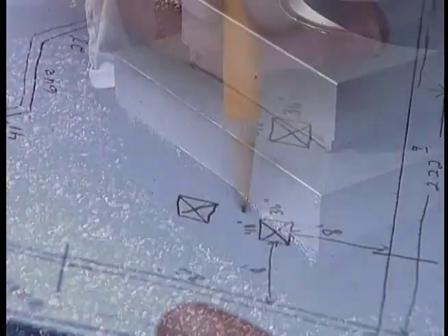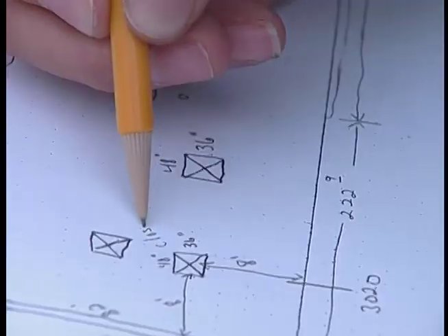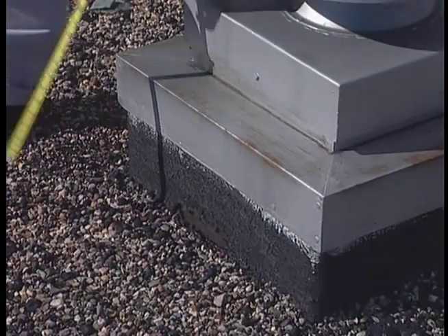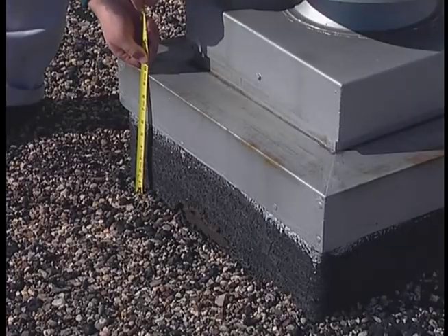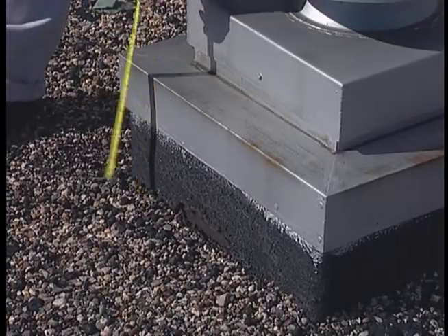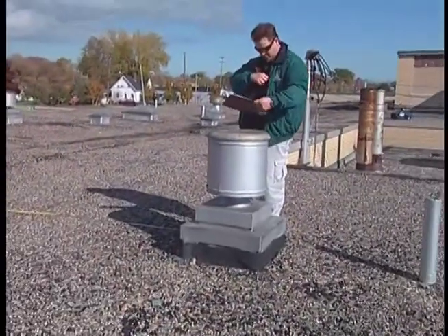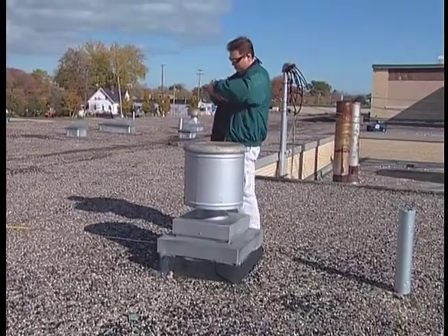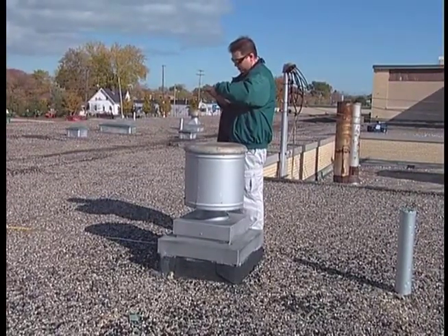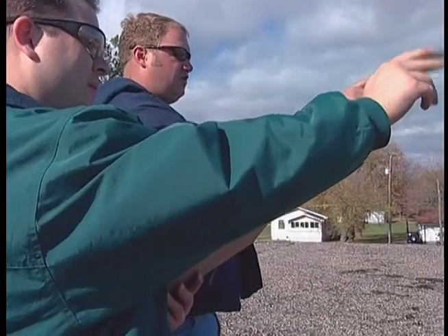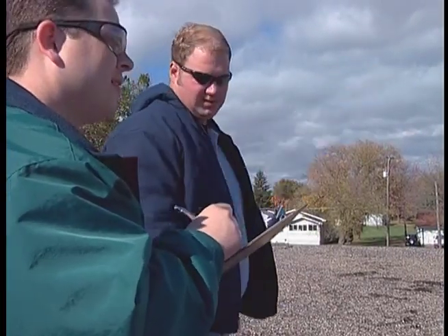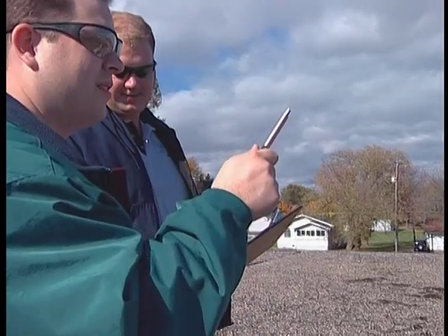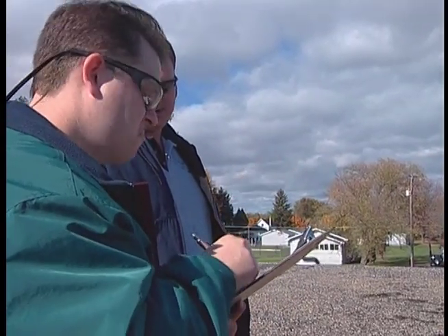Additionally, take note whether the penetration will require an open or closed curb flashing. To decide this, determine whether you can fit the flashing over the unit. If this is possible, use a closed curb flashing. If it is not possible, specify an open curb flashing that will require a vertical field weld. Count the number and note the sizes of round stacks. Write that data on the back side of the order blank. This way you're sure to get all the stack flashings that are needed.